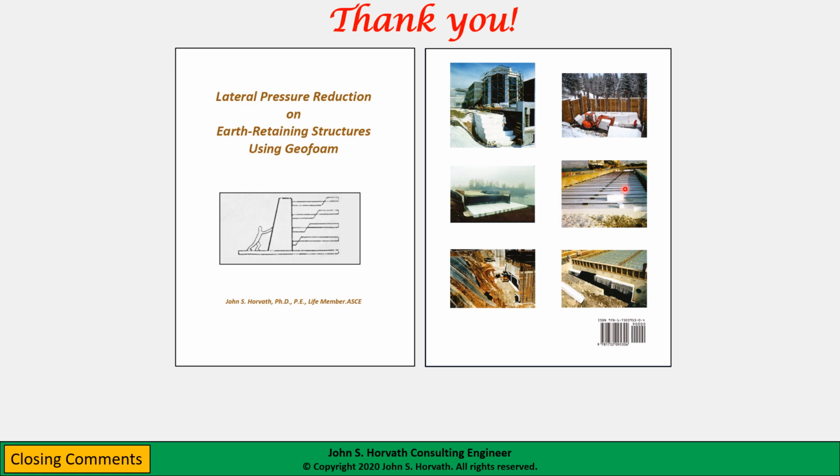This project was in Japan, and it's interesting because it illustrates use of EPS block geofoam to reduce lateral pressures for a flexible earth retaining structure, in this case an anchored bulkhead.